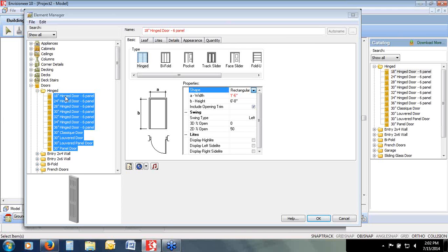With all of those highlighted, their properties appear on the right. I want to draw your attention to the properties that you see in red. Those properties in red are properties that are not similar for all of these elements. Obviously the name is going to be different for all of them. The red color is a flag to say, before you edit this option, you must realize that all of these elements have a different name or a different width. Do you really want to edit them to all be the same? It's giving you a little warning that you might not want to change these parameters that are different for all of these various elements.